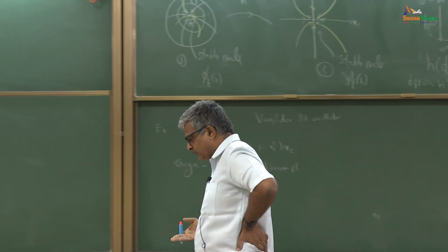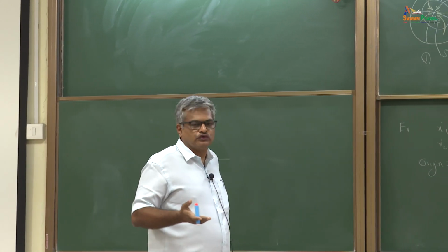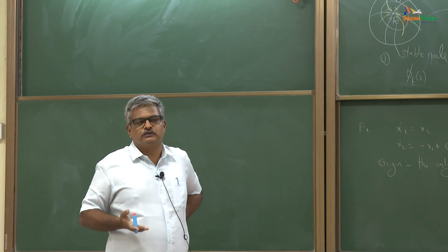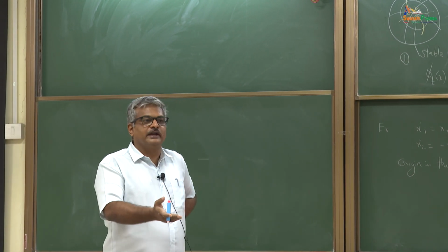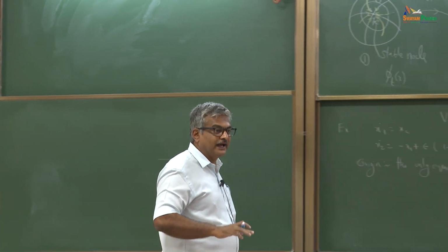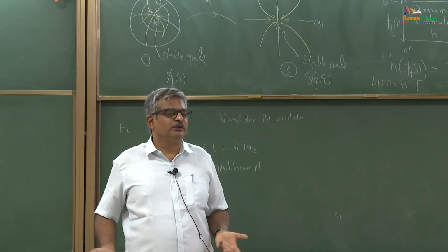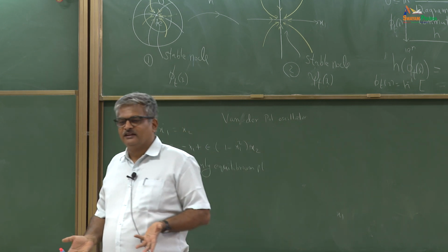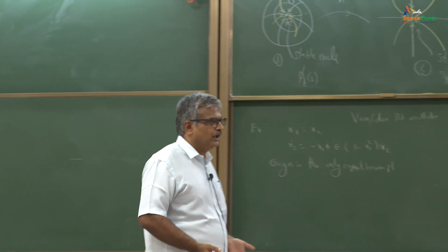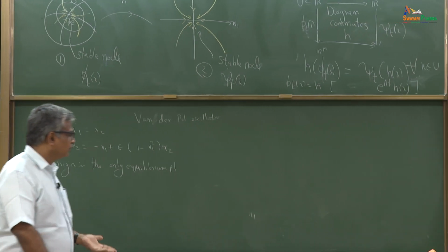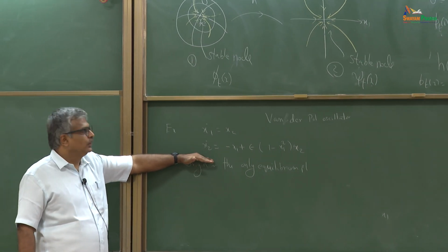And you need an oscillator which caters to some frequency of oscillation, right? Now that you cannot get through a linear oscillator. And the other thing is, you can never construct a linear oscillator. It is impossible to construct a linear oscillator, right? Because non-linearities are inherently there. Okay, so that motivates us to study this nonlinear oscillator.